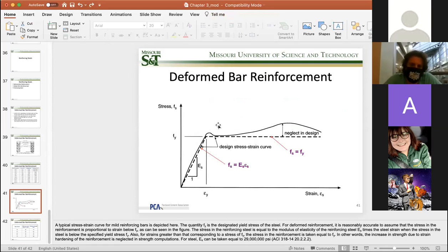The black curve here is the tensile strength result of a single bar. Basically, I put a hook on one end, and pull the other end to tensilely stretch it, and I have a curve divided by the nominal area. Keep in mind, nominal area is the area we start with. I get this stress-strain curve like this. You can see that it follows a nice linear curve, then I have a bump, and then it gradually comes up again and goes down again.